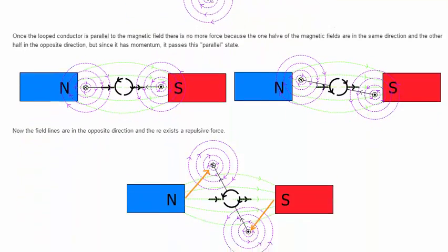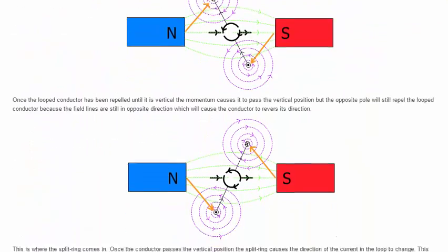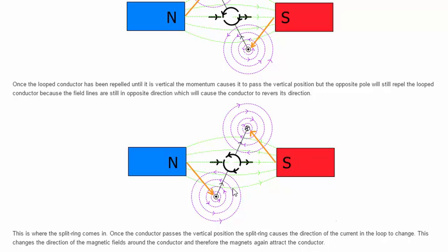Okay, and so that's what happens once it passes here in the middle. You'll see that's where I reach the gaps, but I still have some momentum coming from this side. So as I jump over that gap, all of a sudden, this one used to be connected to that top one. Look, this one used to be connected to the top one. Now the moment I come past here, I'm connected to the bottom one, which means my current is going in here.